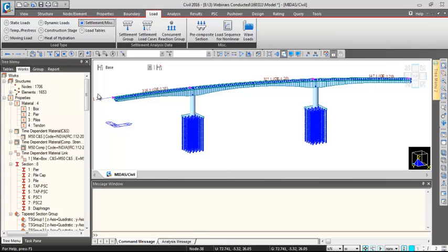So what we have to do is we have to restrict this effect of settlement only to the settlement analysis and not take it to any other load case, because for all these load cases, when we are generating the load combination, at that time we are superposing these loads and we will get the effect. If we are not doing this, then what will happen is the boundary change, the settlement effect would be taken up for moving load, dead load, everything separately, and when you are doing combination, this effect would be multiplied in magnitudes. Okay, so to avoid that, we have to restrict this settlement of supports only to the settlement analysis.